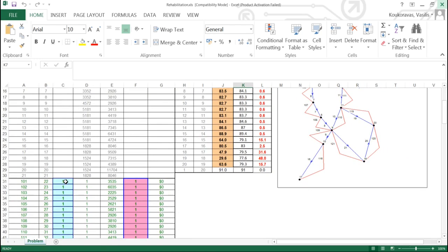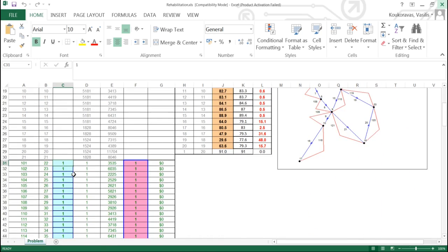The available diameter indices are numbers from 1 to 16. Number 1 means that we do nothing, and then numbers 2 to 16 are the 15 different diameter values that we saw in the handout. So there are 15 discrete values of diameters that we have to choose from in order to add in these duplicated parallel pipes.